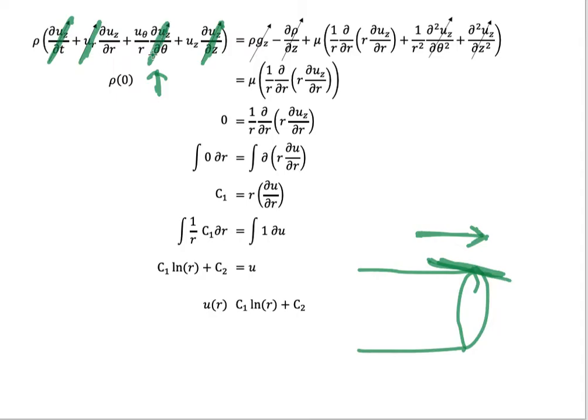At the same time, du dz means the velocity on the z-axis here. Because it is steady, the velocity here and here in the z direction is also 0. And then the gravity is 0. And then we have dp dz, because we assume that normally in a moving cylinder there is no pressure drop. For fluid flow inside a pipe, maybe we could consider a pressure drop, but here it is a moving cylinder, so we assume that dp dz is 0.